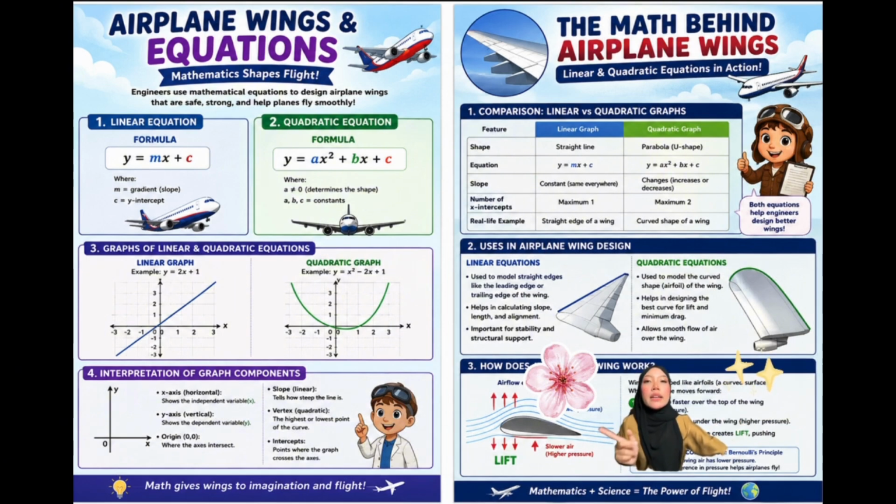airplane wings are not flat. Instead, they have a curved profile known as an airfoil. Why is this curve very important in airplanes? It is because the curved surface allows air to move differently above and below the wing. The difference creates lift, which we will explain later.